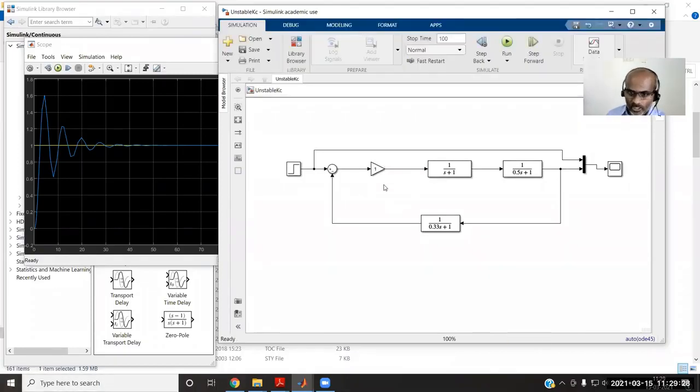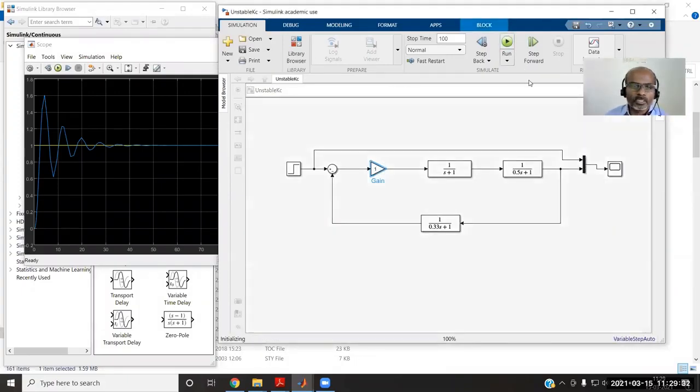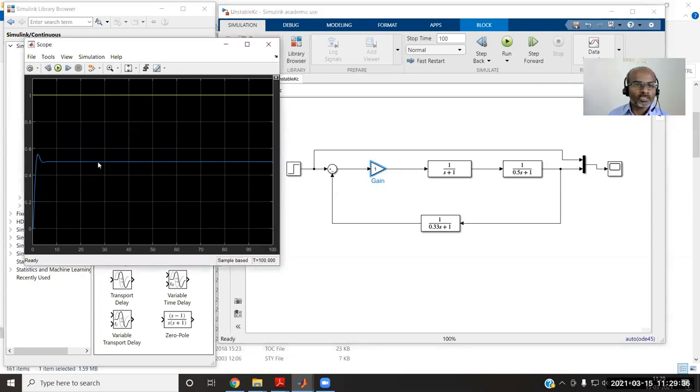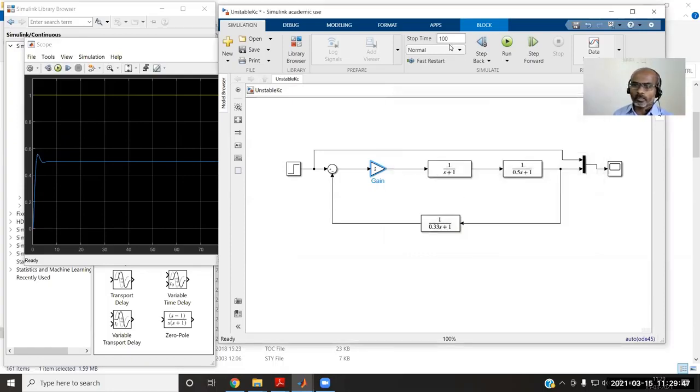the proportional action alone. So for that, I'll again see the response, then only you can compare. So the input is changed to 1, and the output is settling at a value of 0.5. To reduce the offset, we can keep on raising the value of gain. So the offset is now getting reduced. It is somewhere around 0.65, so 1 minus 0.65, or 0.35, is the offset.